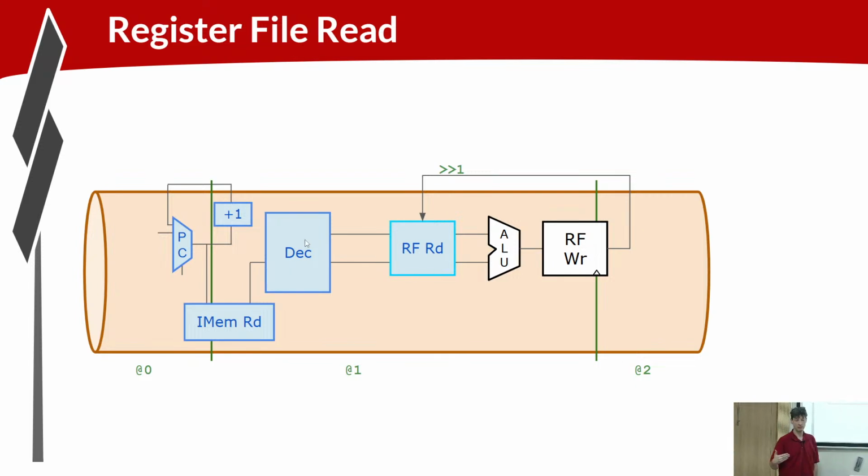Part of the motivation behind the instruction set architecture is to define the instructions in a way that they can be executed efficiently. You saw that RISC-V chose to always put the RS1, RS2 fields in the same place. That means coming out of the instruction memory, those instruction bits with the register file index don't have to go through any logic to get to the register file. They're just a direct hookup straight from the instruction memory to the indices of the register file. That helps to streamline the CPU.